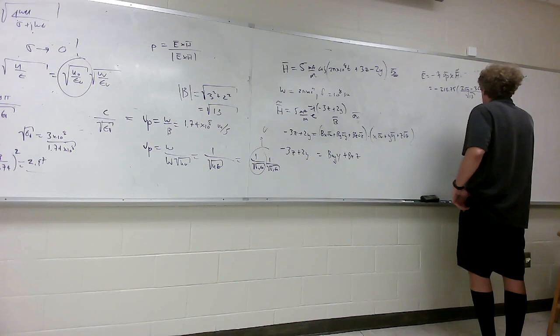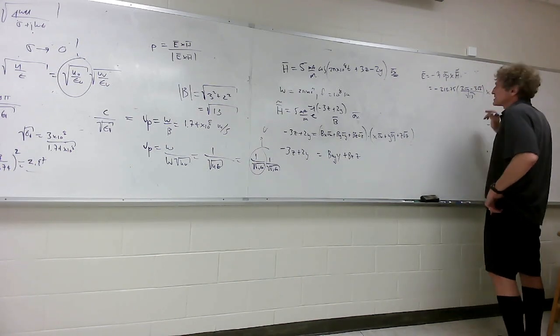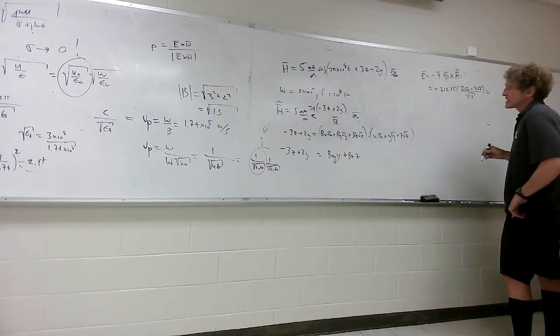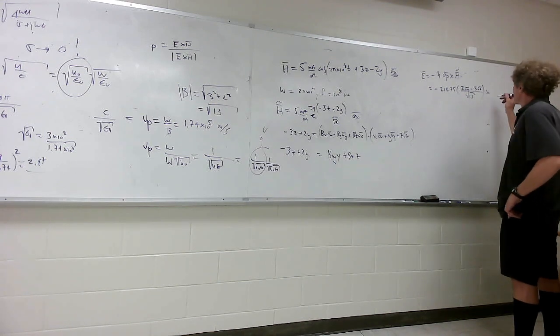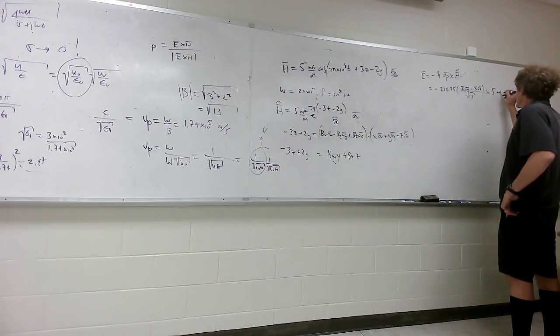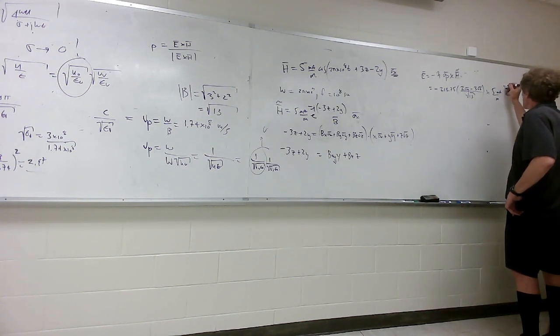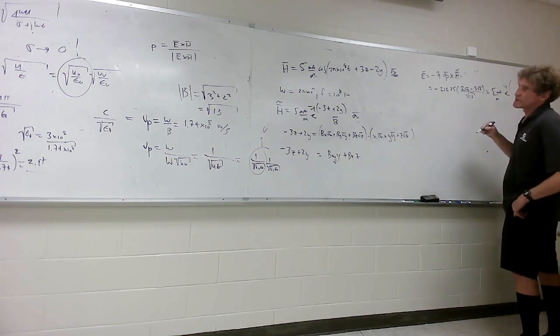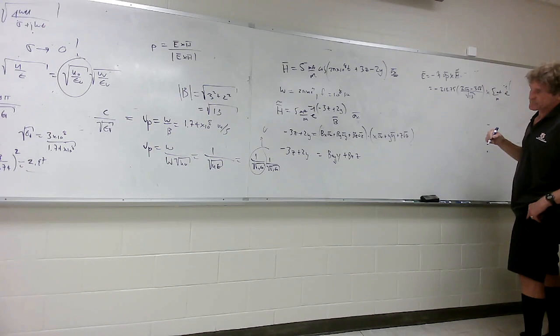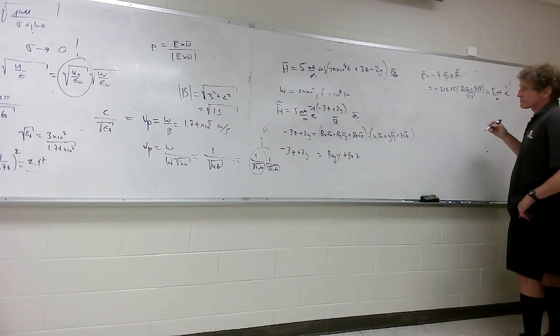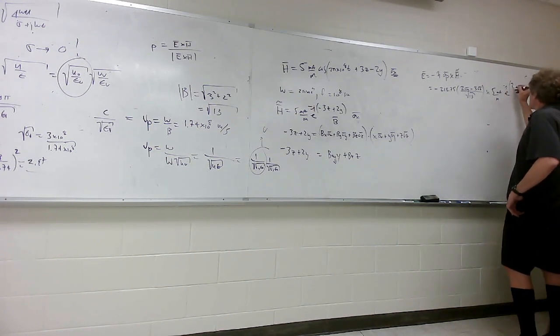All right, and it's crossed into the H field, and the H field right there is in the AX direction. So I can put the whole thing down there, 5 milliamps per meter, and then it's going to be e to the minus j times 2y minus 3z, in the AX direction. Follow me?